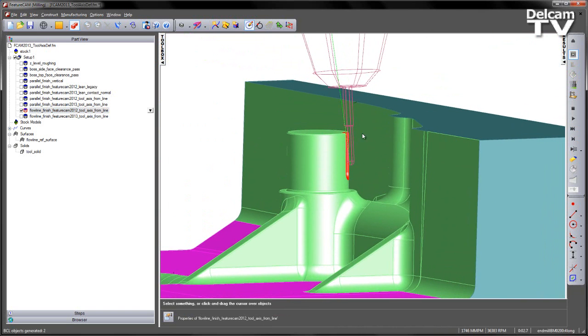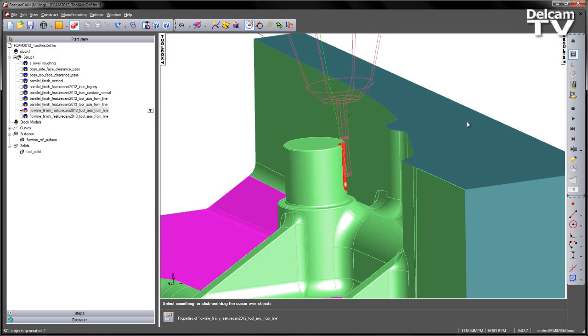but again we can see the issue because the toolpath axis is created based on the flow line reference surface, not on the surfaces we are projecting to. If we play that through, we can see the tool was orientated incorrectly.